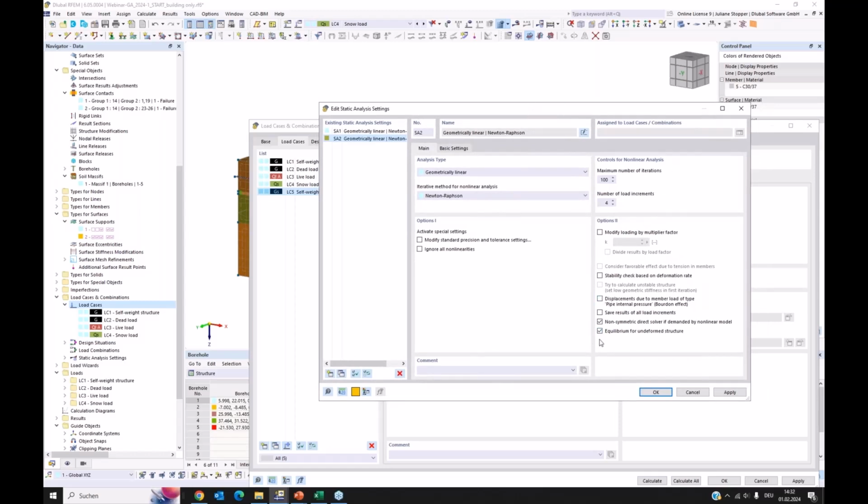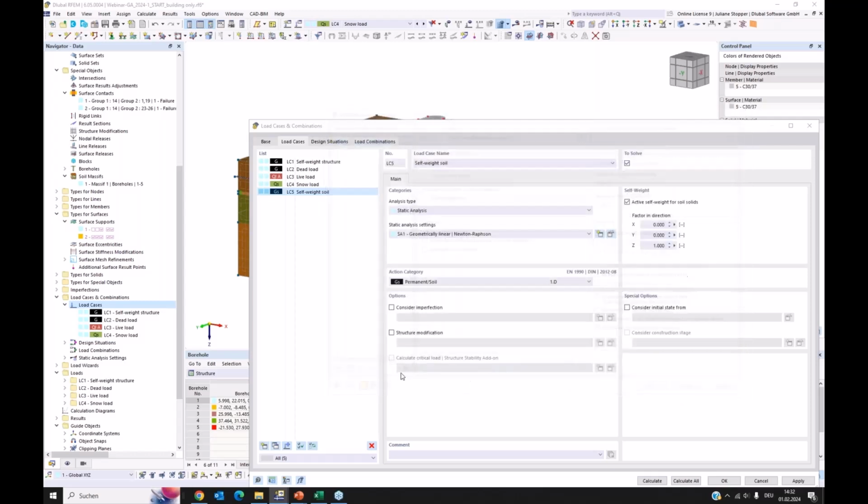With this setting, our structure is solved, it is loaded, and the stress state is calculated, and the deformations that are calculated are reset to 0. That's why we write for undeformed structure. So this is perfect for our initial state. I will rename it so I can understand later more easily. It's actually SA1, but for undeformed structure. Call it like this, then we know it's nearly the same setting.